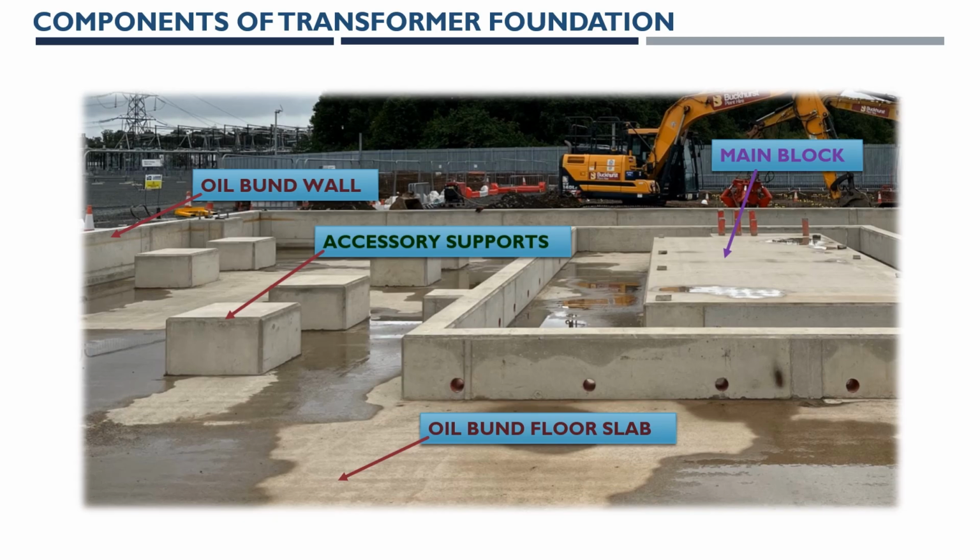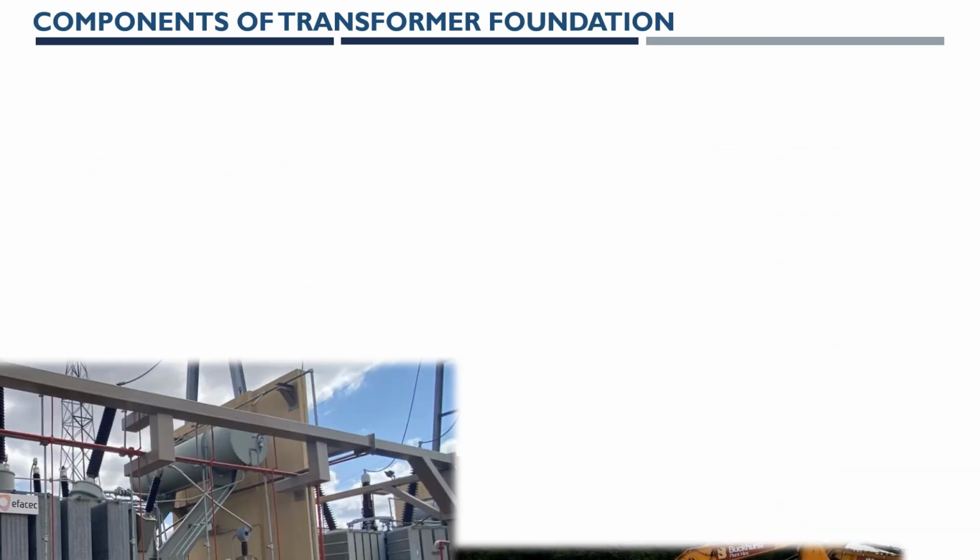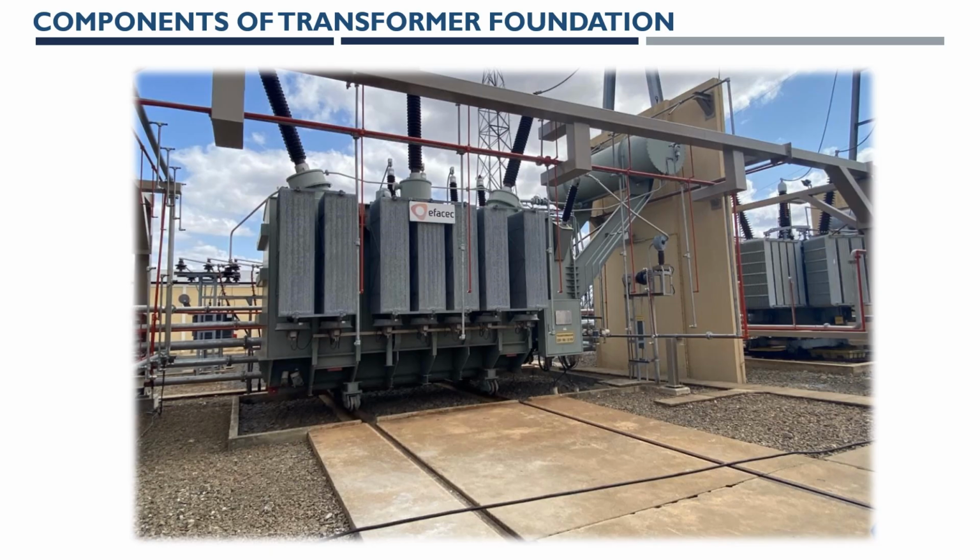In this picture, these are the supports for cooler support, radiator support. This transformer has rollers at the bottom, so the rail should be inserted inside the concrete, and the concrete slab is placed near the transformer bund, so that this concrete slab or rail cum road can be extended to the nearby access road. This is to be designed along with the transformer foundations.